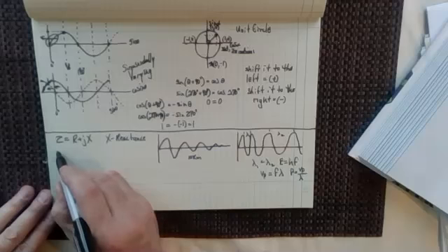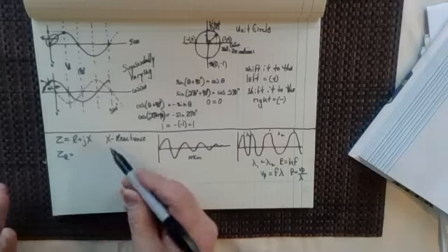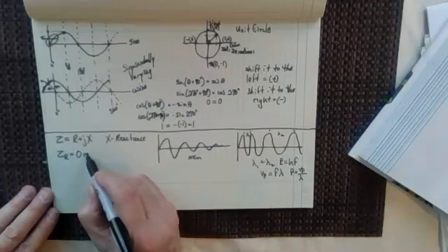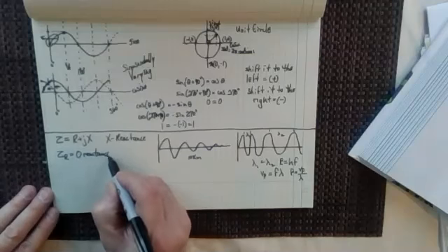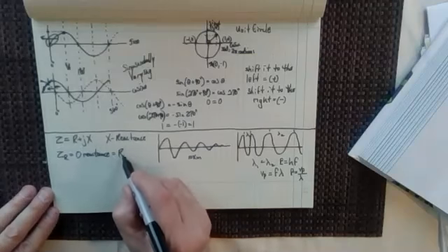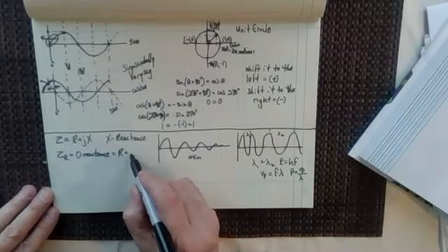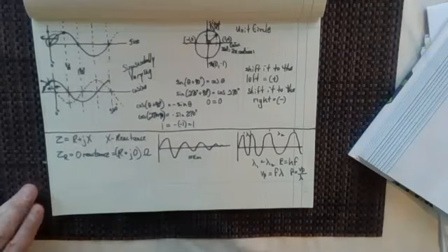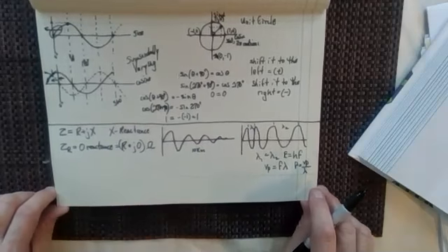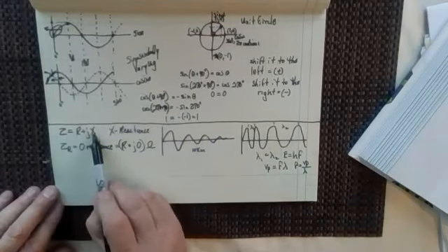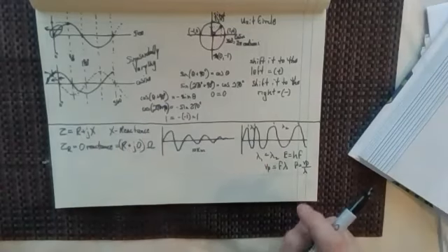And so let's look at the three different impedances. For the impedance of the resistor, we know it has zero reactance. So if I was to write this out, that would be resistance plus J0. And what are my units? My units are going to be in ohms. Impedance is in ohms, resistance is in ohms, and what do you know? Reactance, guess what, is in ohms too.